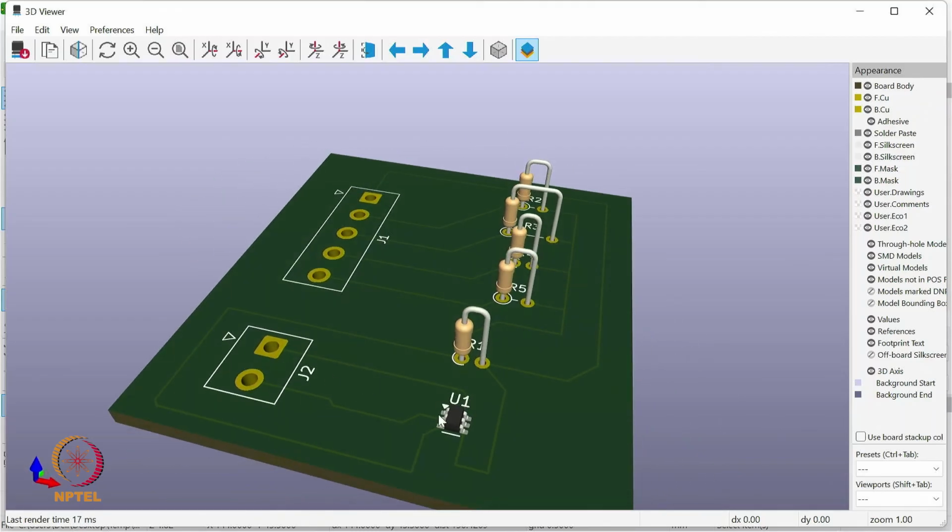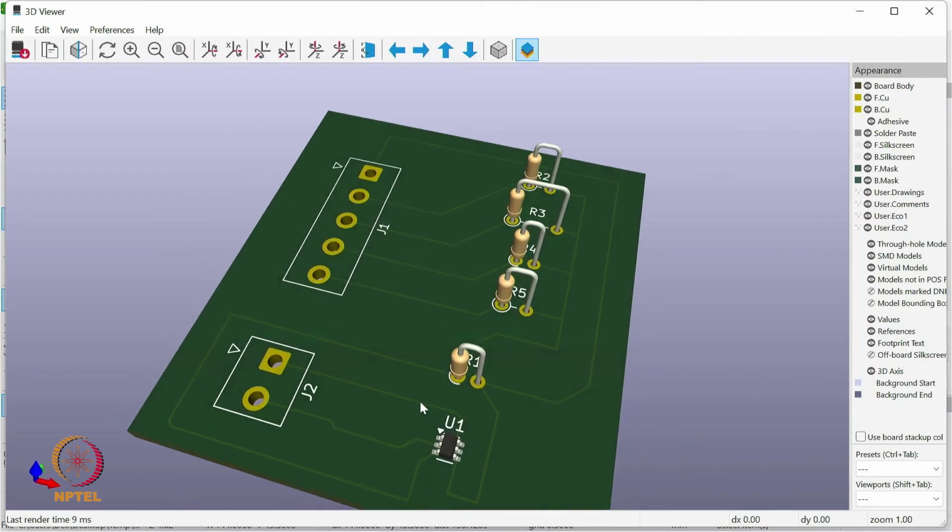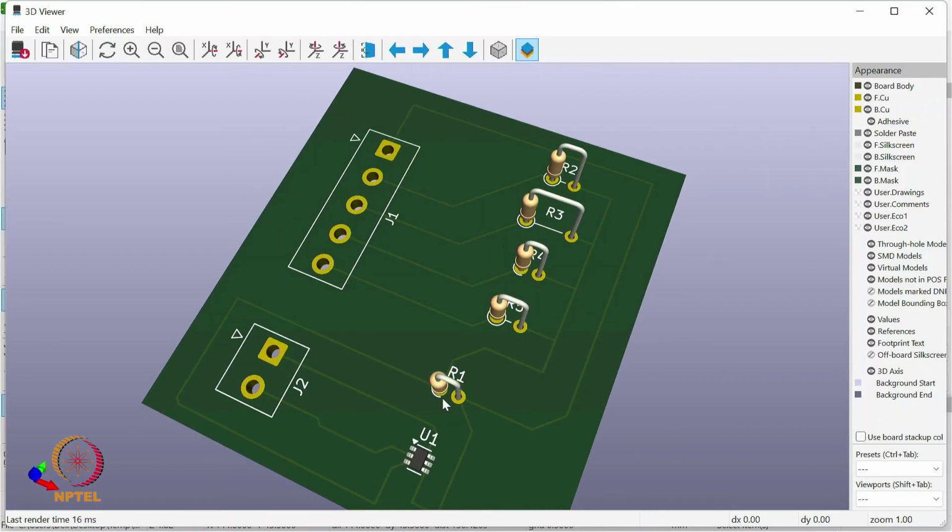So this is our OpAmp IC. These are all the resistances. This is R1, which is the feedback resistance. These are R2, R3, R4, R5, the signal resistances. These are the pins where we will connect V1, V2, V3, V4, and the output will be taken at this pin 1. Similarly, the power supply to this PCB will be provided by this GND connection here and the supply at this square pad. So this is how the final PCB is going to look when we fabricate it using some manufacturer assembly.